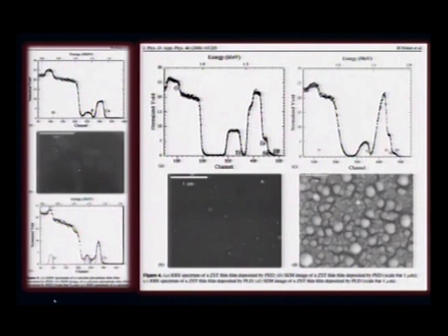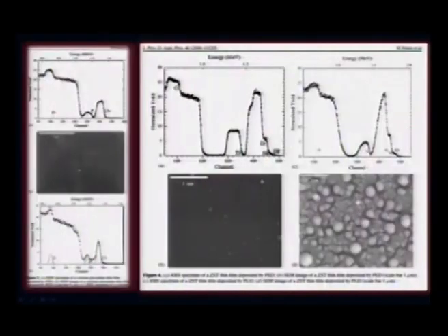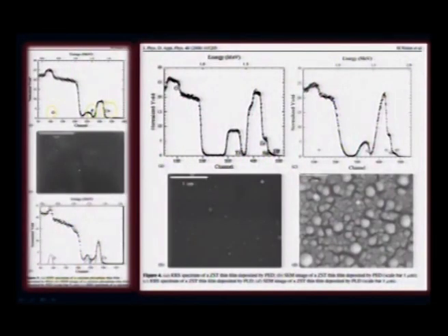This cartoon tells us what is the gamble with the stoichiometry. So in such conditions, what is the stoichiometry of the final film? For example, in this case, this is a RBS, Rutherford backscattering spectra of your calcium phosphate, which will actually estimate how much of calcium is there, how much of phosphorus is there, and how much of oxygen is there. So you can technically evaluate your final composition based on the RBS channeling studies. That is the advantage. And as you would see, the solid line here is nothing but your theoretical prediction, and your dotted line is nothing but your experimental plot.